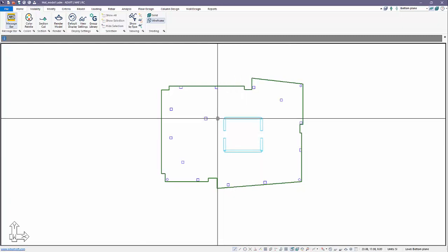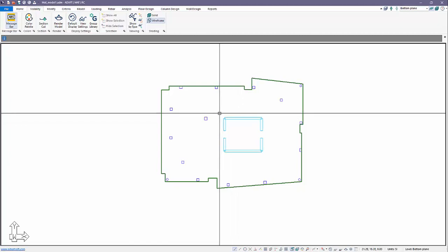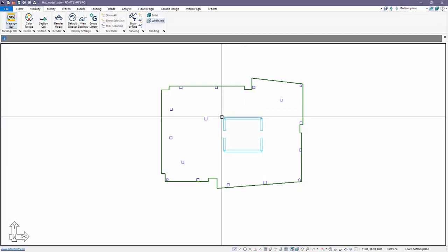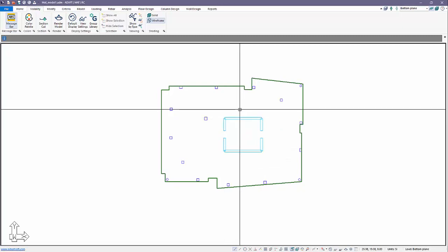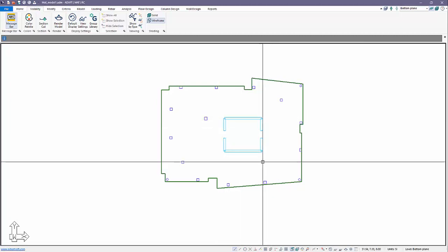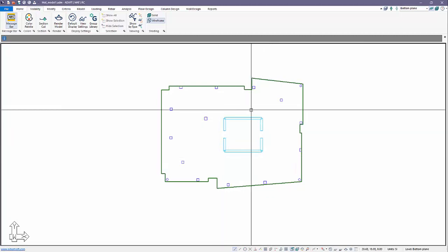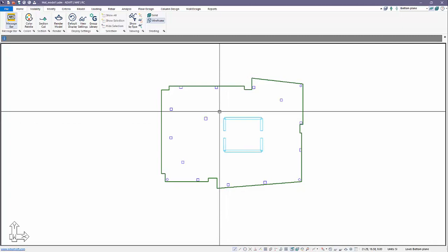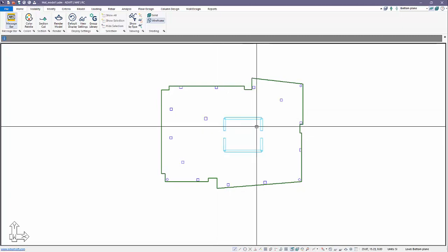So we want to have, let's say, an extension of this overlap at some distance away from the edge of the walls. We need a way to actually reference those points, since the CAD file did not contain a polygon where we would model that thickening. We're going to offset the overlap by 1.5 meters from each wall face.